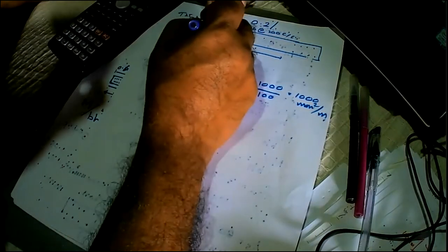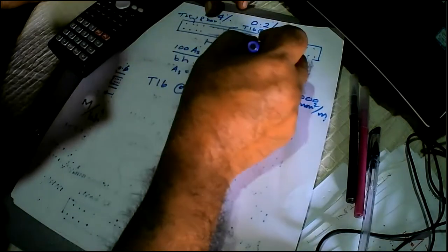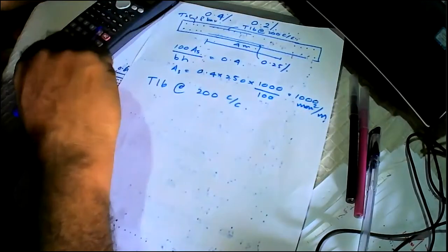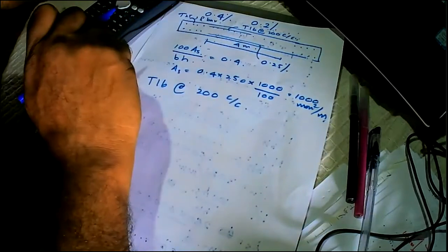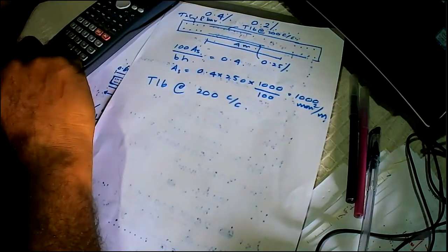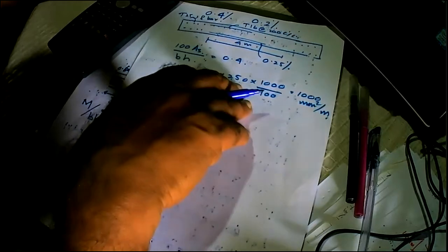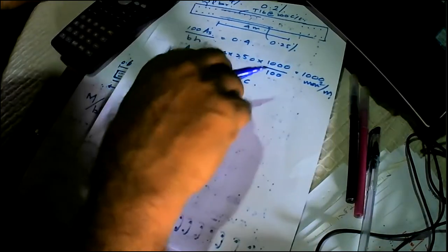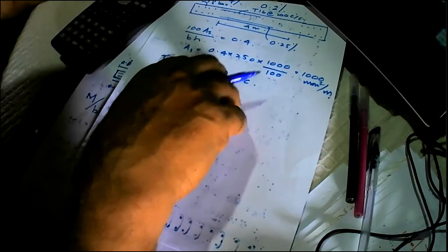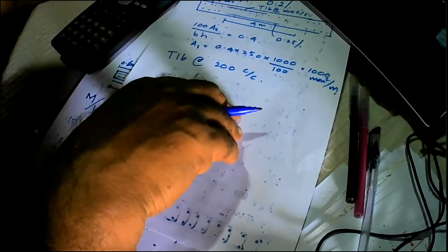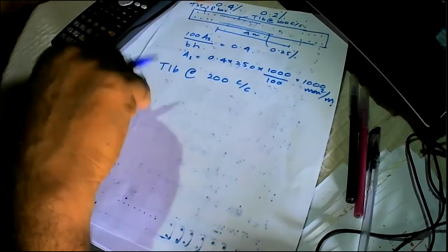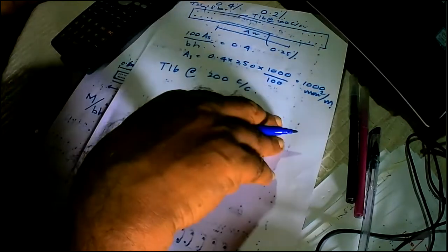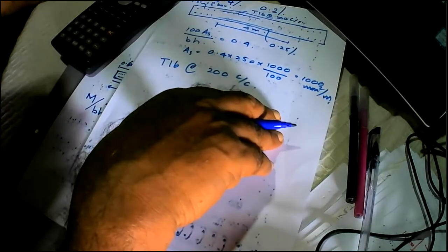And in the horizontal direction, generally we provide 0.25% reinforcement. 0.25 means, when you add the reinforcement on both faces, you should end up with 0.25. So that is one way of actually providing reinforcement when the moments are known. So when the moments and the axial forces are known, that is one way of actually providing the reinforcement. Is it clear to you?